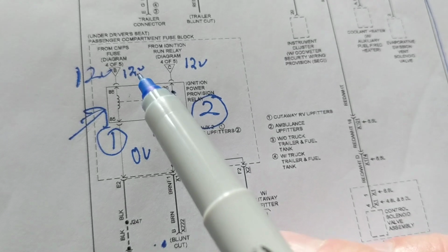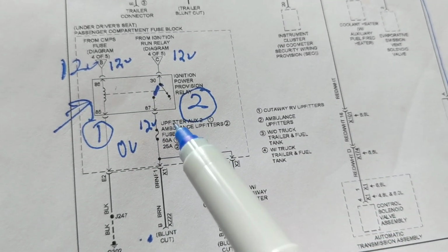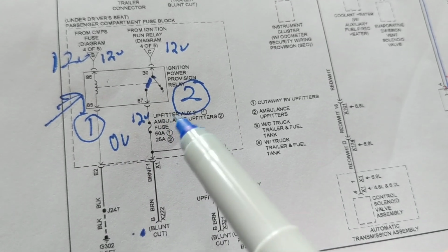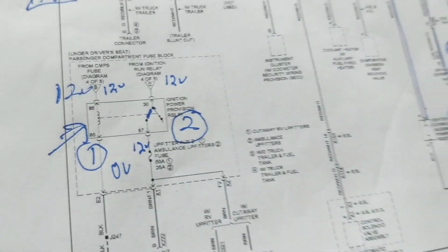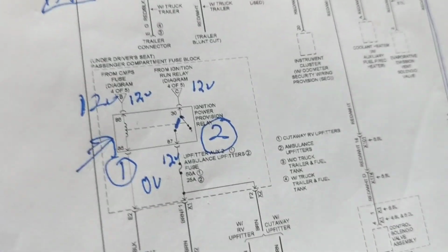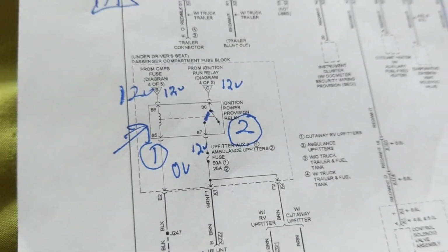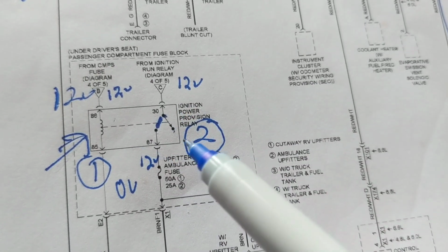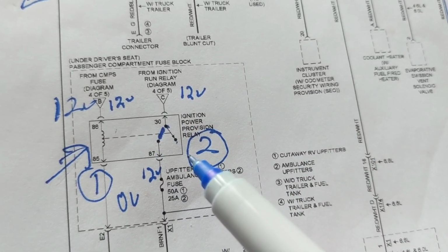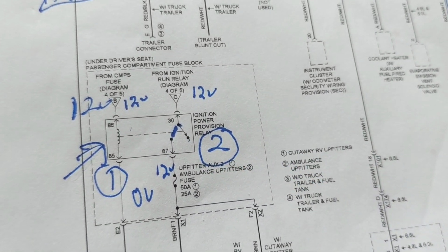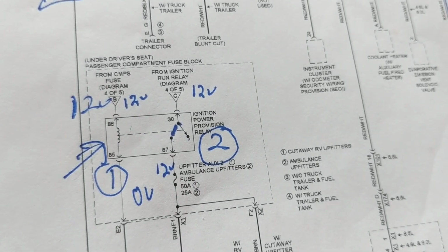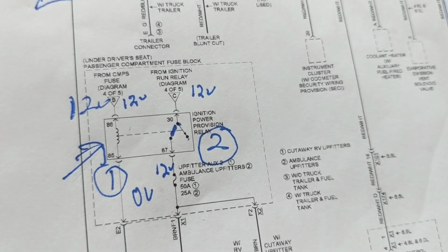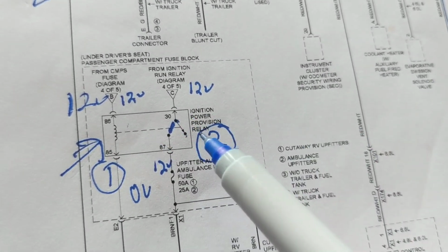If you see many other videos, they take out the relay. They say, okay, we measure 12 volts here. We measure 0 volts over here at the ground. We measure on the load side. This is what I'm saying. When it comes to electronics, you measure everything in circuit. You measure the relays in circuit. You do not take out the relay. To me, that is absolutely of no use whatsoever. It absolutely accomplishes nothing. So all the videos that say, let's take out the relay because we can't